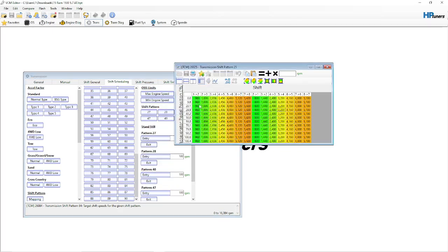So again, let's say first and second gear, here's 900 to 1600 RPMs, and the truck is not going anywhere. The optimal power band is probably going to be somewhere around 3500 RPMs. It really should be shifting right around 2500 RPMs here in second gear. Honestly, this whole column needs to be shifted and moved over here to the left, in my personal opinion.